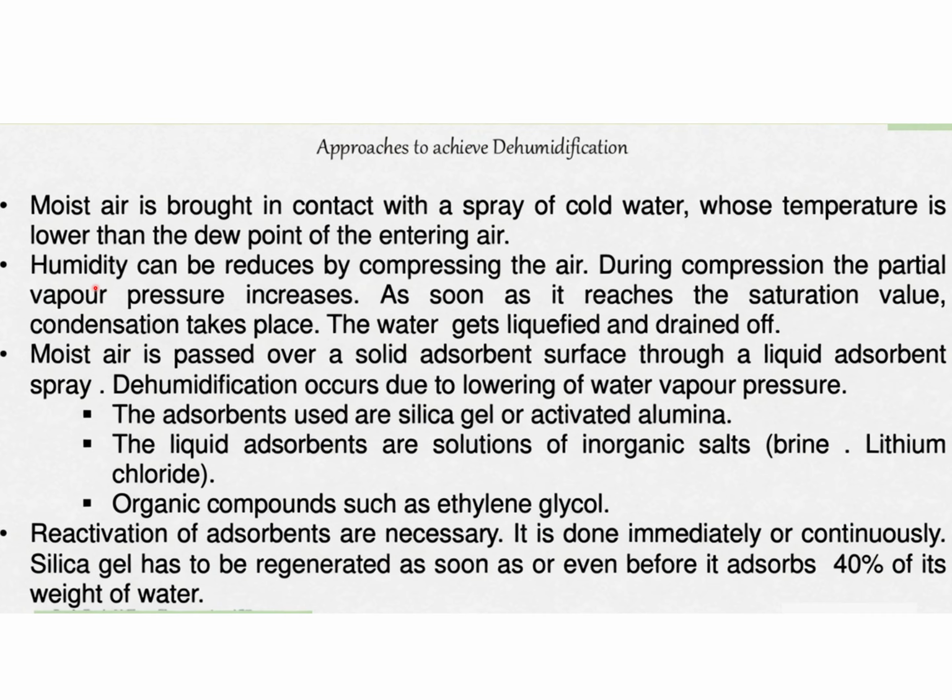Humidity can be reduced by compressing the air. During compression, the partial pressure increases. As soon as it reaches the saturation value, the condensation takes place. The water gets liquefied and drained off.